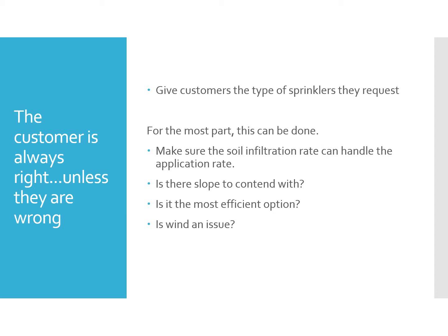And then also, is this the most efficient option? Is there an alternative sprinkler that may work just as well that has a higher efficiency rating? If so, you may want to hear them out, hear what they have to say about the sprinklers that they want, and then also offer them some alternative options and explain the efficiency of the suggested sprinkler versus the sprinkler that they would like.